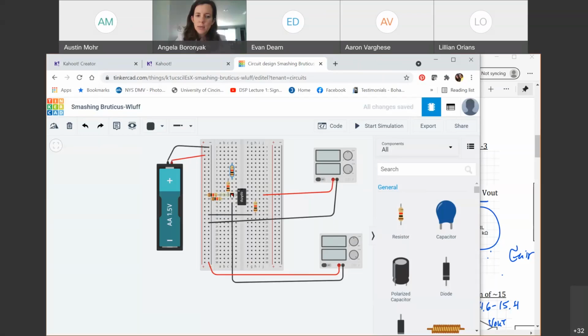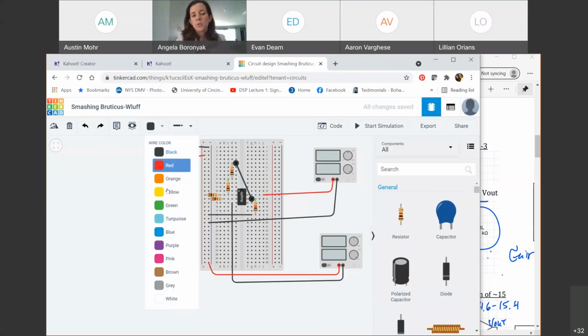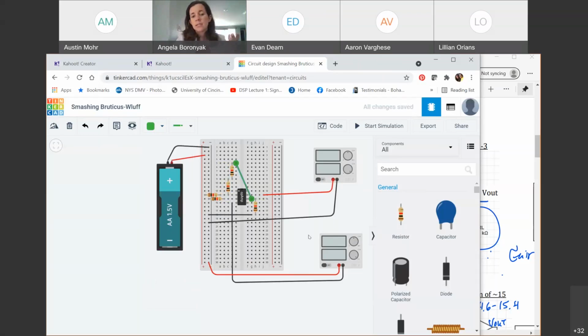What does in series mean? Same current. Go from one to here, then these are connected, and then from here to here, right? So this would be like 2 resistors in series if I do that. You can keep building with 3, or you can go across, however you need to do it, but you do need to check that the equivalent resistance in series makes that RF, right? To go from here to my output.